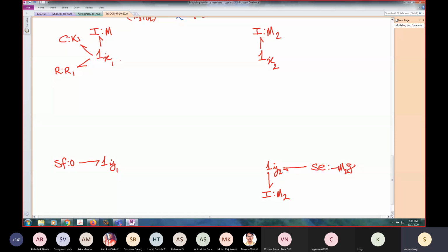So we will do that same kinematic relation. Let's take x1 dot minus x2 dot. How? Zero junction. So here it is x1 dot, here it is x2 dot. We have x1 dot minus x2 dot. We could have taken x2 dot minus x1 dot. It's fine, no problem. But the power direction should not be such that it becomes x1 dot plus x2 dot. It has to be either x1 dot minus x2 dot or x2 dot minus x1 dot, one of these. Then of course we will put a transformer.